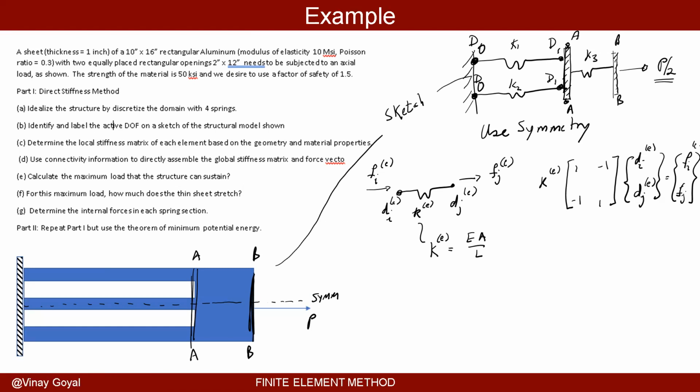That displacement needs to be calculated in the problem, right? The node j for the springs K1 and K2 is the node i for the spring K3. So it means that the same displacement happening at the nodes j for K1 and K2 is the same displacement for node i in K3.